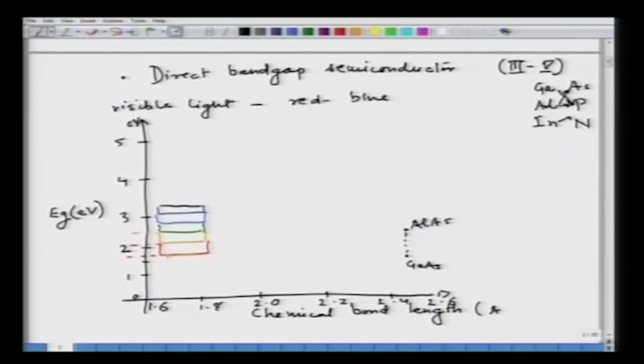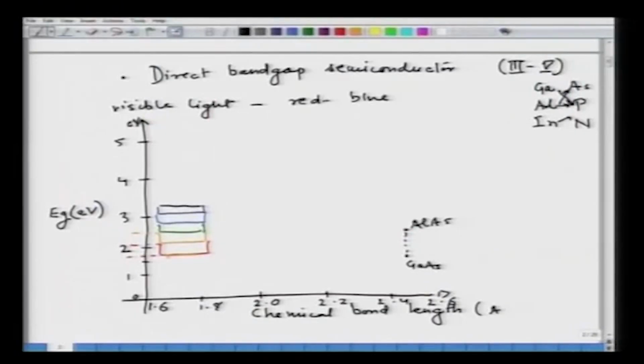If one looks at it all the way going from gallium arsenide to aluminum arsenide, although we are changing the aluminum to gallium atom, the lattice parameter of this particular material does not change, and this is a very good thing from a device point of view, which means I can always make a combination and make a material which is going to be gallium aluminum arsenide in a certain composition when gallium is X and aluminum is 1 minus X. So, I can go through all compositions from gallium arsenide to aluminum arsenide, and X will change.